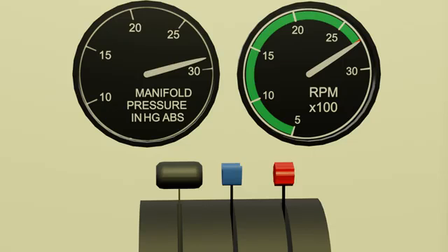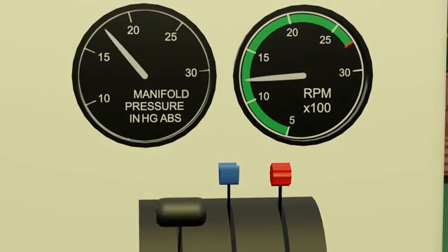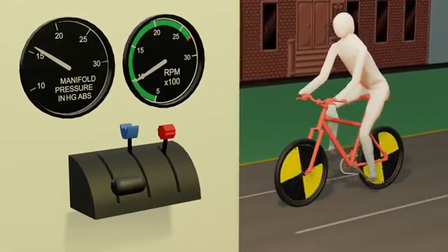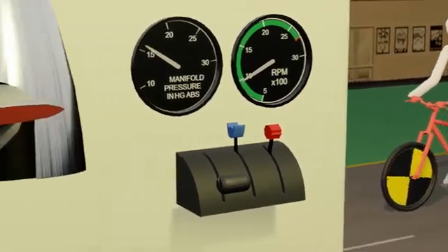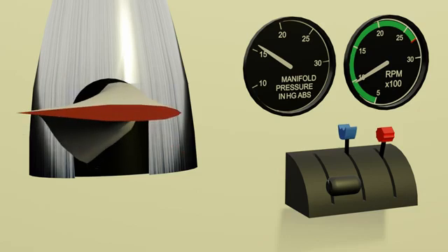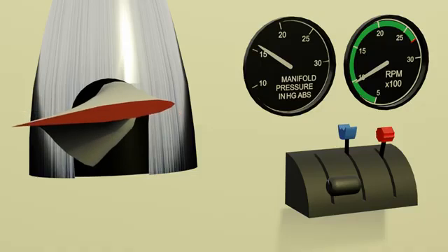Okay, we've made a great landing with throttle idle and propeller fully forward. When riding a bicycle slowly, you'd rather be in low gear, pedaling a little faster and easier. Similarly, the blades are in fine pitch, and the throttle makes the engine push lightly to generate the little thrust that's needed to taxi. The blades also rest on their fine pitch stops at low RPM. Otherwise, the governor would push the blades all the way to an ultra low pitch and generate zero thrust. The fine pitch stops make sure the blades continue to take tiny bites out of the air on the ground.